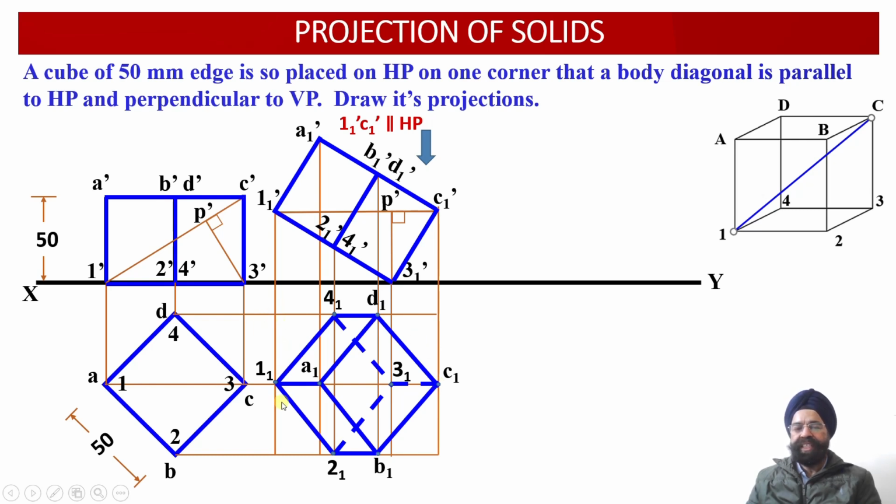So now this rectangular shaped figure which inscribes the top view projection we have just obtained has to be rotated 90 degrees so that A1 C1 should be obtained over here. So this rectangle we have to transfer at an angle of 90 degrees with respect to the vertical plane.